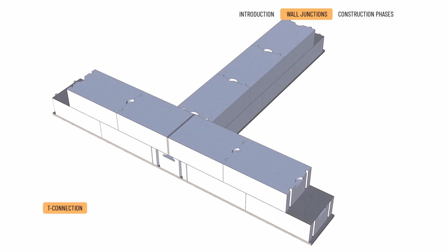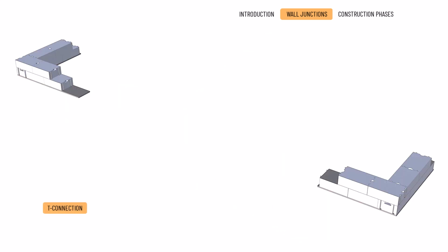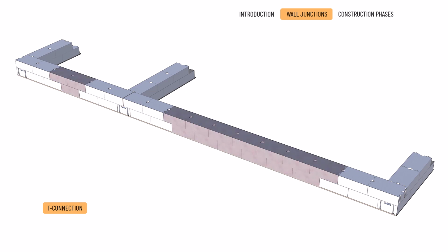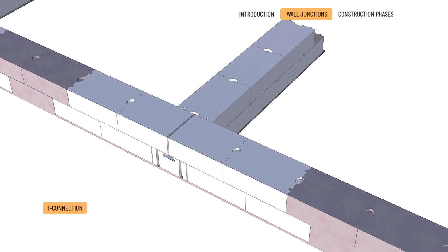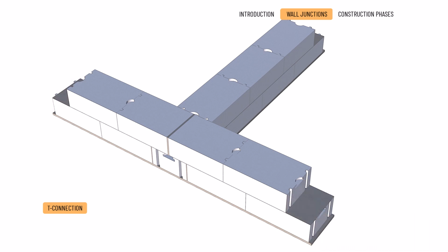T connection. In our example, we assume that our main wall section already contains 2 wall corners, bonded as described earlier, with whole element distances from the corners to the sides of the perpendicularly adjoining wall. Based on this, the bonding overlaps are 22.5 centimeters in both directions, in a symmetrical setting.